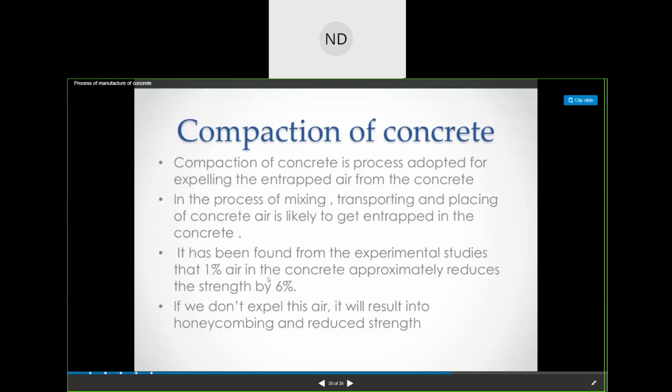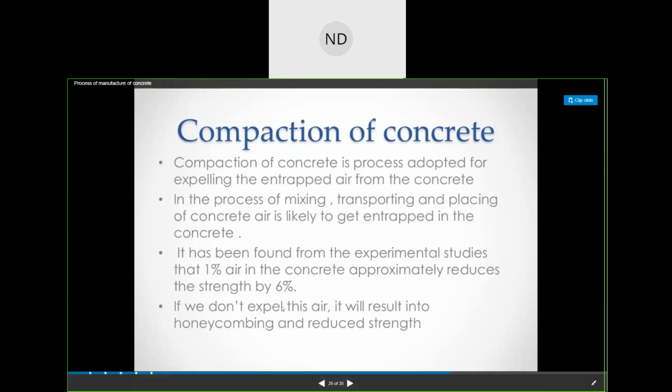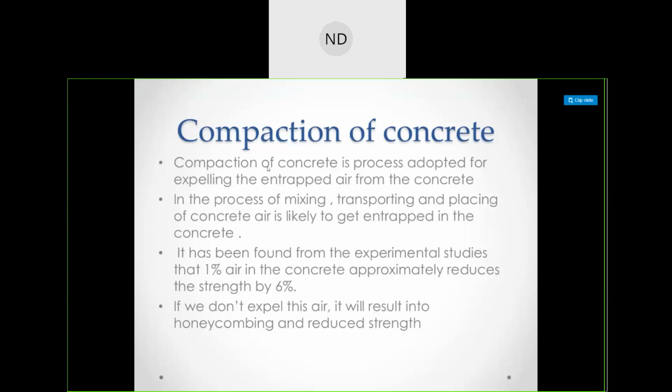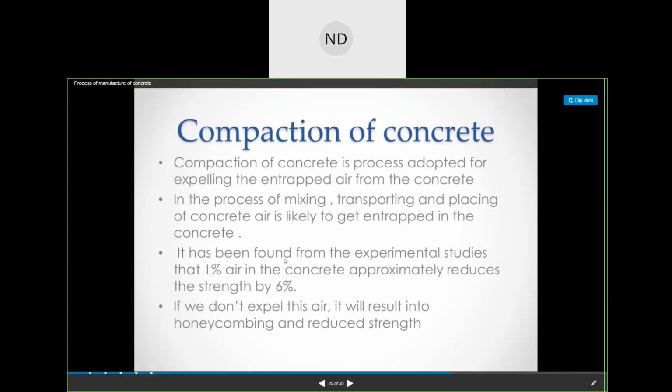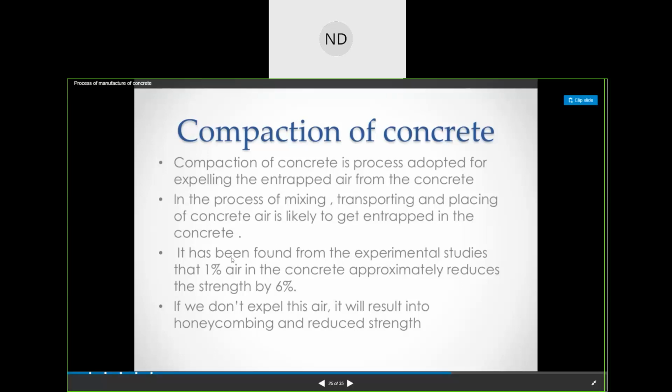So we don't want the strength of the concrete to get reduced anyhow. So we do the compaction to remove the entrapped air, so that our concrete remains at its own strength. It does not reduce its strength due to the air entrapped in the process of mixing, transporting, and placing of the concrete. Because if we don't expel the air, it will result in honeycombing or reduced strength of the structure.